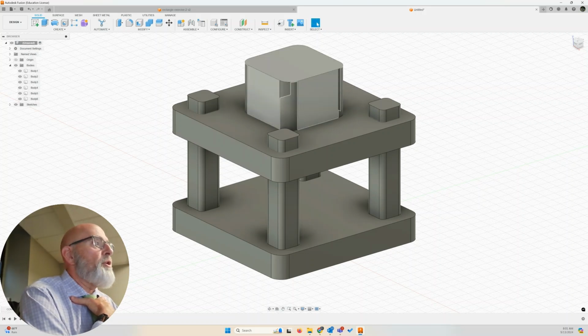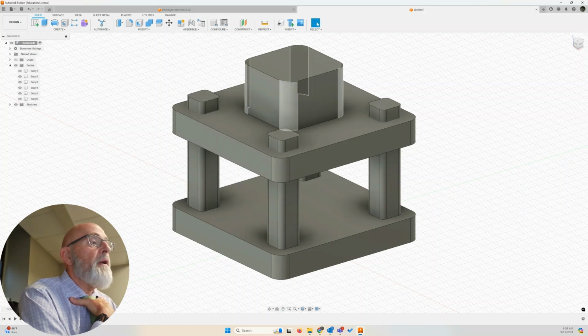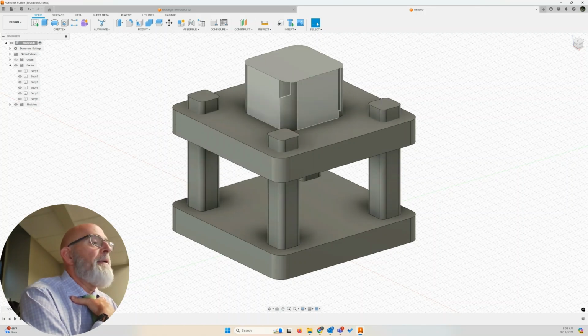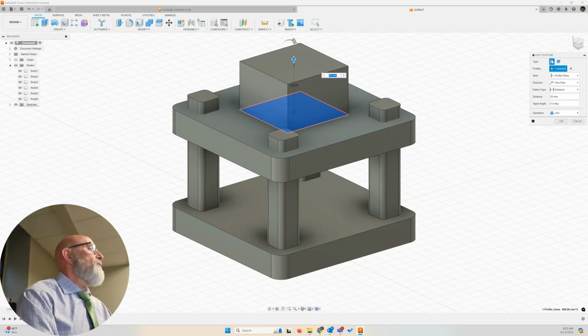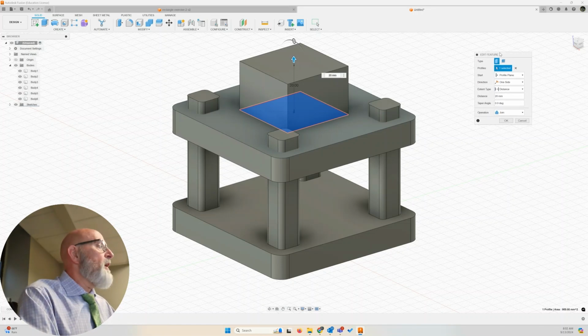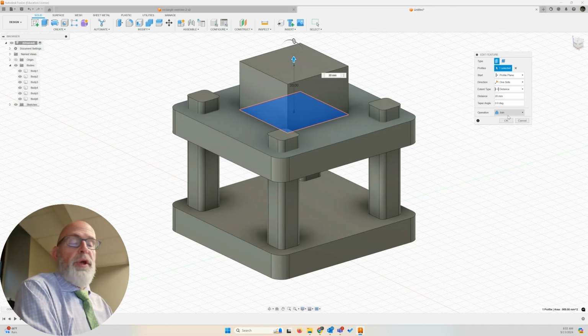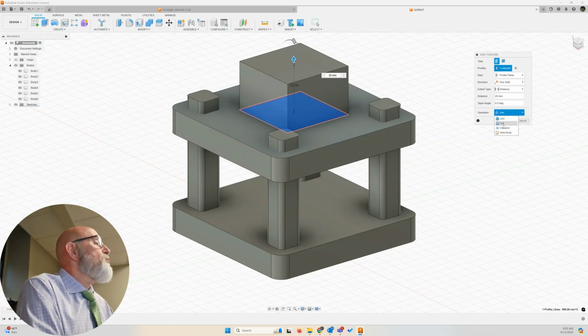There's my extrusion. When I hover over the feature, these items, these 3D effects, are called features. I'm going to right click. There's the extrusion. See how it highlights the extrusion? I'm going to right click, edit feature. If it were a sketch, it'd be edit sketch. I did gloss over it. It's a join. Let's change that from join to new body. Click OK.